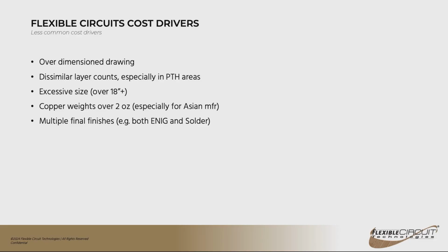Do you have capabilities to do printed flex circuits in polyester substrates? We can, but there's not really a good reason to do that. The only reason you'd ever use polyester is to save money, and polyimide will outperform it across the board.